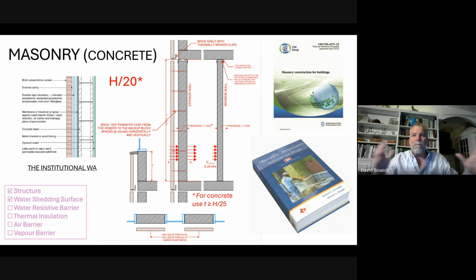So there's not a lot of air movement. It's a pressure difference between one space and another space. It can also happen due to a mechanical system kicking on. You get a fan evacuating air in one room and not another room, which can generate interior pressure. The rule that we use for most interior pressures is 0.24 kPa, which is 5 pounds a square foot, which is a very small load when you're looking at a small area, but accumulate that over a big area and it's actually significant. So we design most interior partitions for 0.24 kPa.